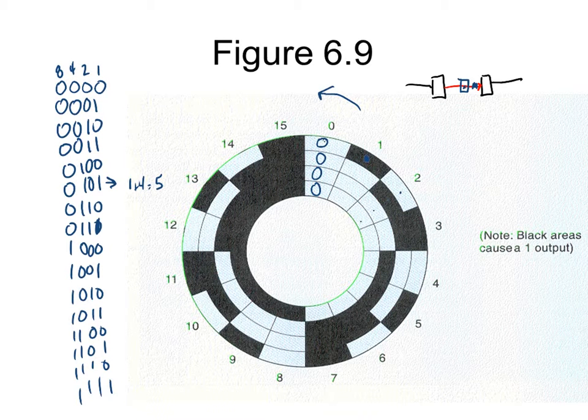So you notice this would be 0. Well, look at this one there. The 1's covered up, so that would be that code right there. So if this is where my sensing head was, when this thing rotates and gets into this position right here, it would say it's at position 1. Okay, now look at this. This would be a 0. So this would be 1, 2, 4, 8. So right here, this would be a 2.